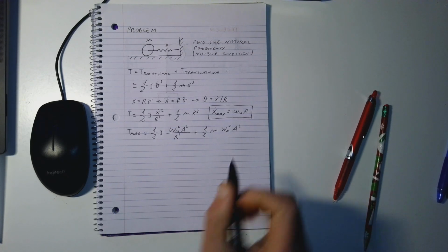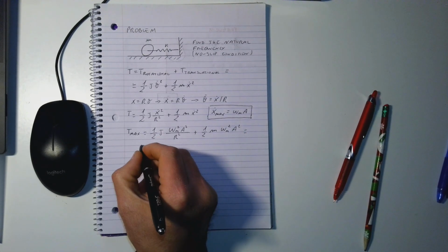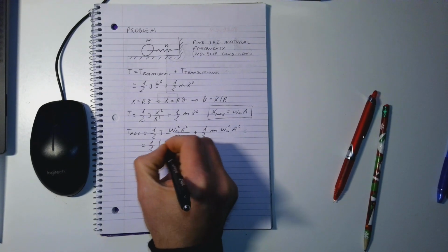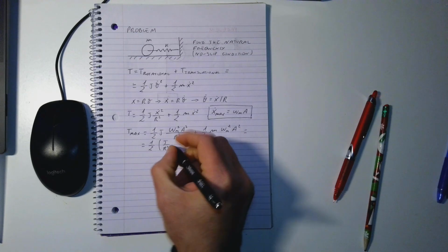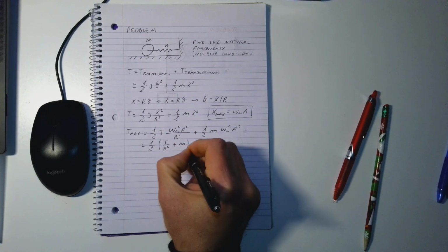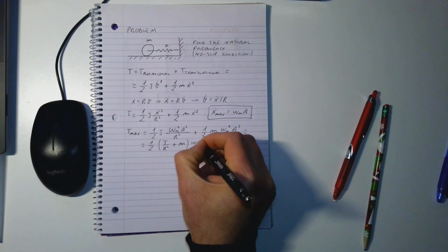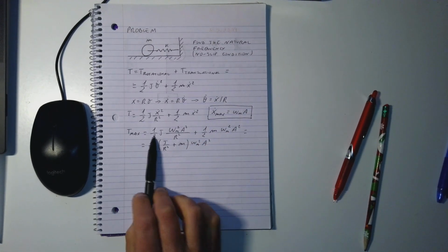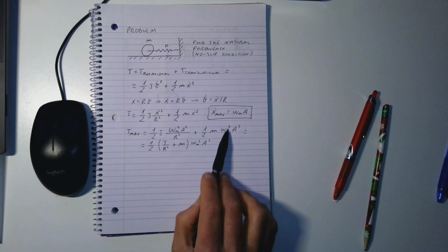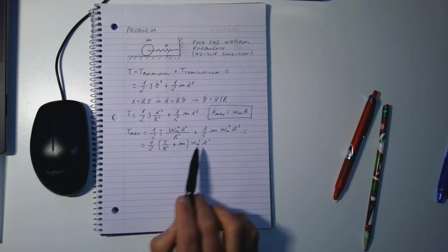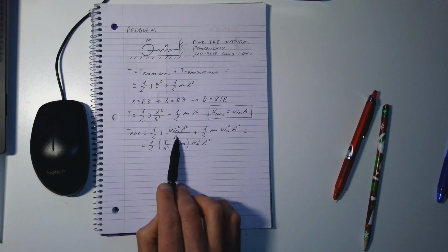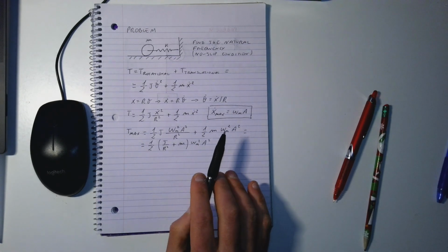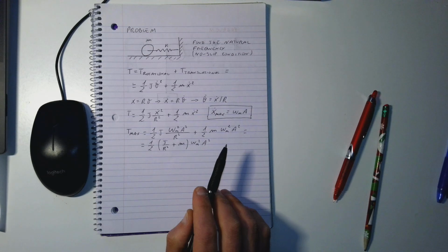We can group things together, so what we obtain is 1 over 2 j over r squared plus the mass multiplied by omega n squared and then a also squared. So 1 over 2 is on both sides, omega n squared times a squared is also on both sides, so we are left with j over r squared plus m. And this is the maximum kinetic energy in the system.